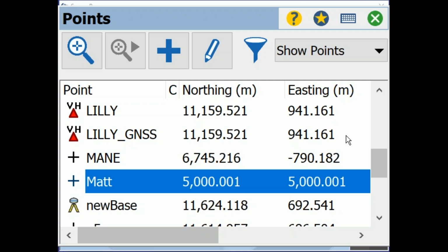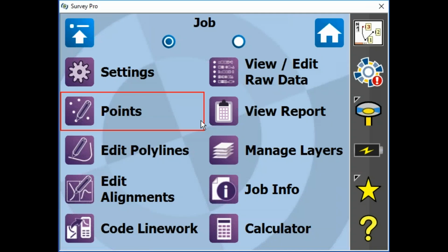I can pick a different scale reference. I can take it higher. I can take it lower. And it's a transformation that is kind of exact. And what I like so much about it is that it preserves the true mapping plane coordinates underneath, but it allows you to work in a ground scaled system. So when you measure 100 on your total station, it's 100 when you inverse it on the grid. But underneath, it's still calculating in the exact proper mapping plane. And it allows you to switch back and forth.